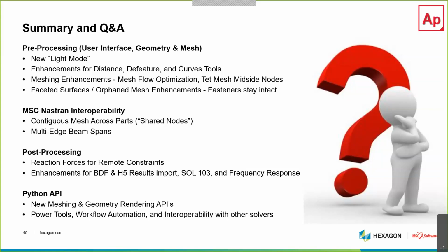And then just like normal, like if you had the geometry to start with, you would go in and do things like defeaturing and changing and pushing and pulling and everything that you already know and love in Apex. Now it's supported because you just did that one small little operation, which is taking the mesh and back calculating the geometry from it, and that's our high level solution to orphan meshing.